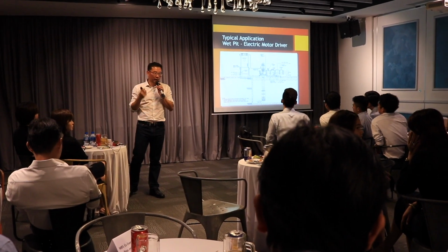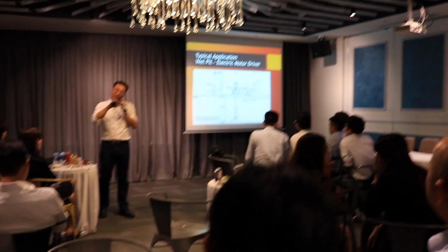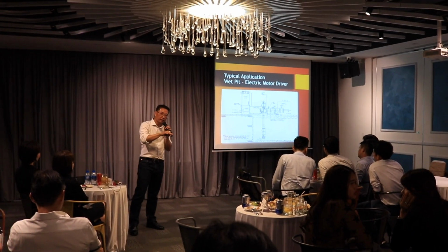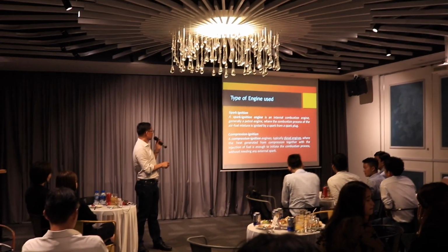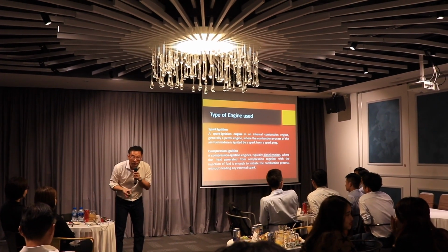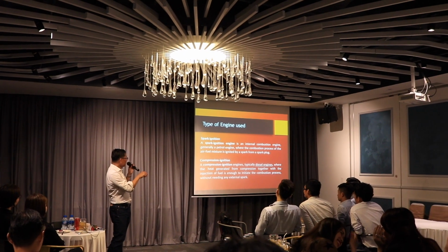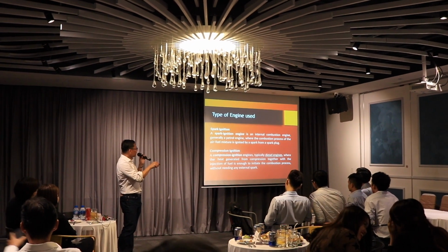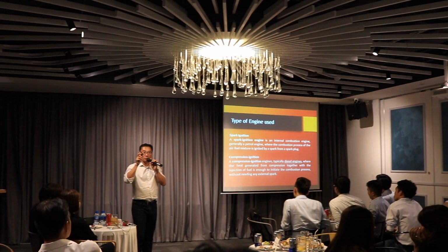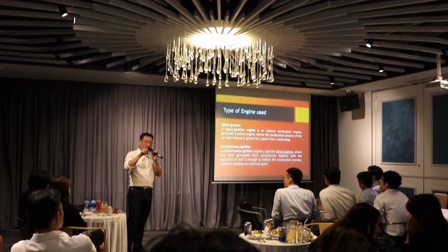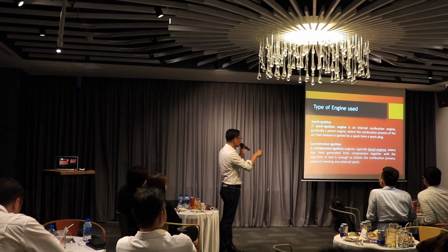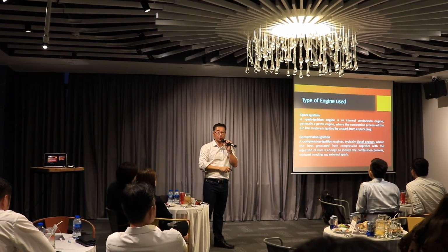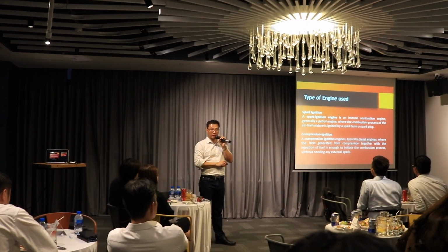As I said, the main goal of NFPA 20 is to understand the code, and understand who is certifying and all that. Alright? Okay, engine: we talk about spark ignition and compression ignition. Any fire pump that has a diesel engine, you cannot use spark ignition; you must use compression ignition. Okay?